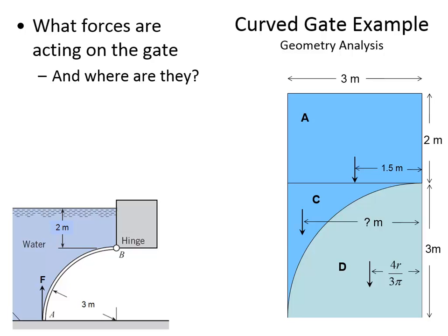So it's the horizontal forces that are pushing on the gate. What do we use as the distance, the moment distance between B and the location of that force? Yeah, right. The YCP is all the way from the water surface to the location of the force. And so if the moment distance is to the hinge, we need to subtract 2 meters. And so it was 3.7143 from water surface to location of the force, and it's 2 meters from water surface to B. And that's why the moment distance here is 1.7143 meters.